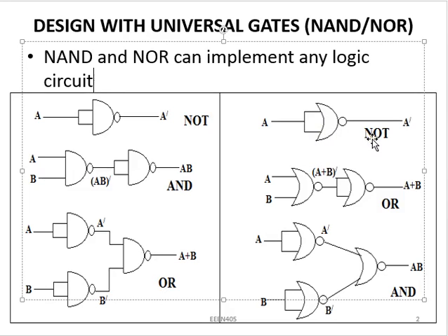And using NOR gates, this is how we do it. For an inverter, we do the same thing. We connect the 2 inputs of a NOR gate together and we connect them to a signal A, and the output should be A prime. For us to obtain OR, all we need to do is to get NOR gates, deliver A and B to it, which will give us (A plus B) prime as an output. Now if this one enters the next stage of a NOR gate, it will be (A plus B) double prime, which is equivalent to A plus B, the OR gate.